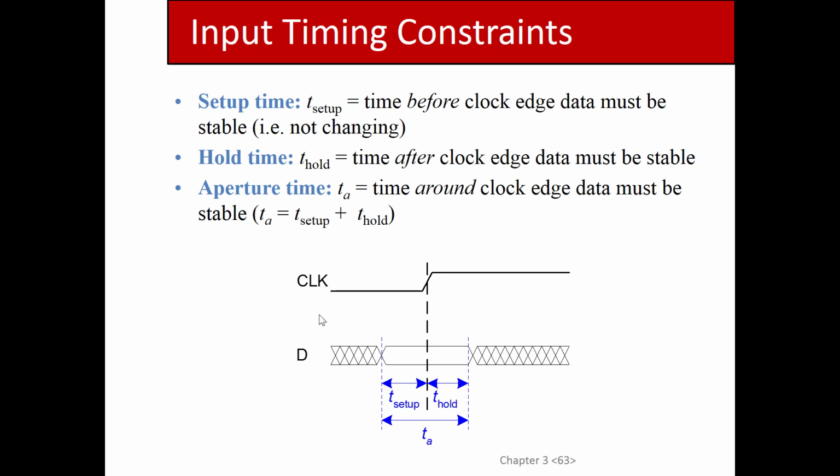I guess you could with a simple thing like this, but generally speaking, what I'm talking about now are rules that have to be obeyed by a compiler, essentially a synthesizer that takes hardware description code, which we're going to cover in the next chapter, converts that to logic, and the sequential logic that it generates has to obey these timing rules.